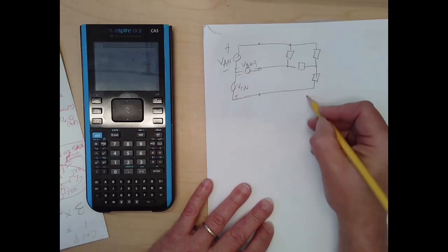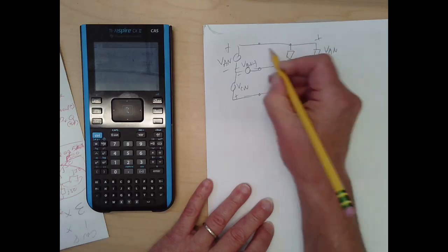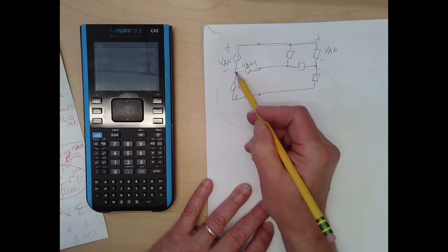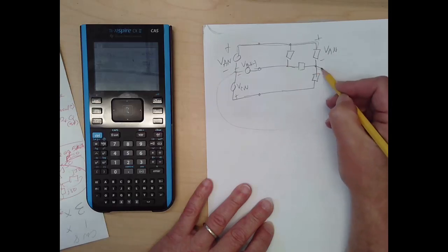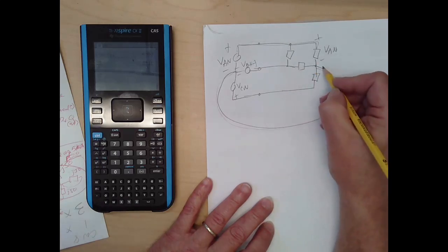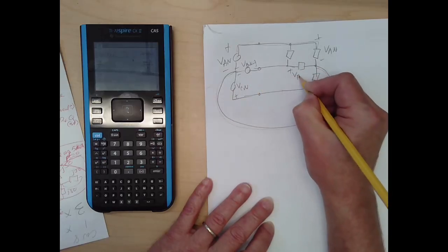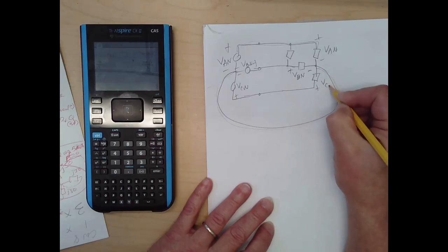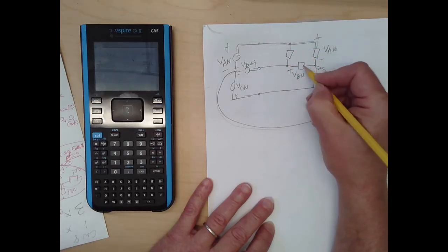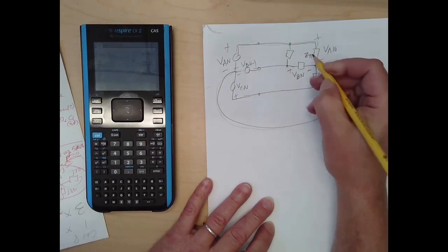It is the same as the voltage at the loads also, right? So this voltage here now is also VAN because there's no drop across the line. So this node is all the same, and we can assume the neutrals are connected, so let's go ahead and put a neutral in there as well. So it's the same neutral on both sides, and VBN and VCN are also the voltages at the load. This was load 1, had balanced ZY1.